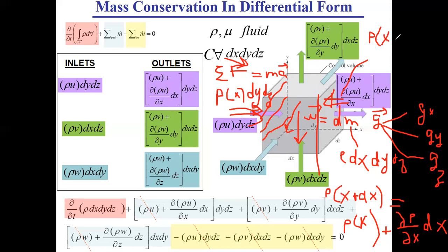Now, for pressure forces, you will consider pressure on all surfaces. As we did for pressure here, you will do it for these two faces and for these two. So you will obtain all pressure forces acting on your element. Also, you can add stress if you want shear forces. Shear forces are forces parallel to your faces.